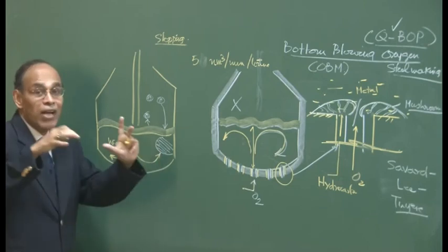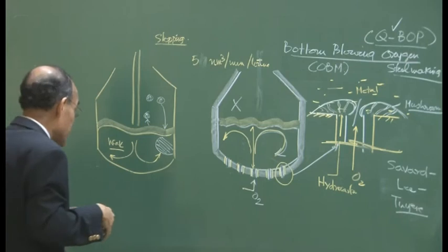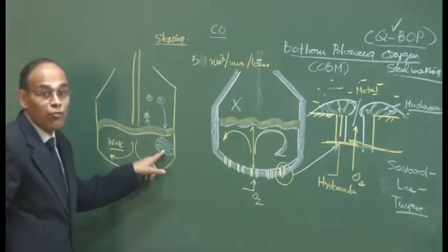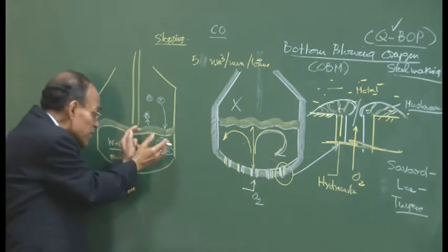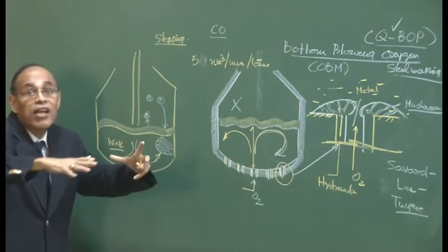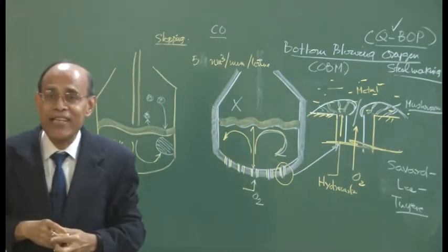And at one point of time, there is a vigorous explosion which may take place, generating carbon monoxide bubbles, because you have a large amount of carbon. All this carbon present in this pocket of hot metal has all of a sudden been exposed to atmospheric oxygen, and as a result you have a huge volume of carbon monoxide generated.